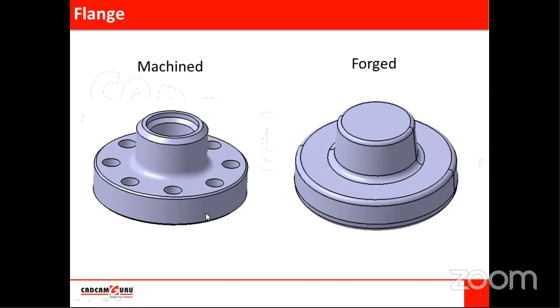After deciding the parting line, we have to apply draft angles, required tapers. We know that for different materials we need different draft angles, right? So we will apply draft angle there. Then we will apply these fillets on these corners. These are the fillets actually, not corners. These are the corners, these are the fillets.